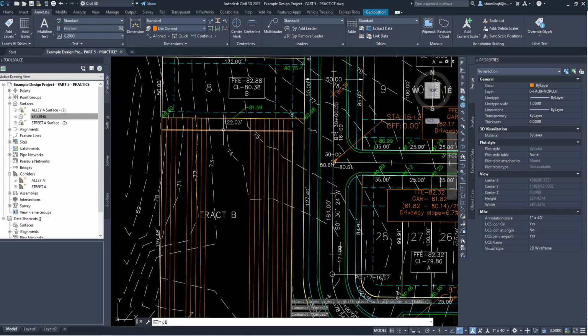So it's basically going to tie into, if I go 69.6 minus 81.59. So this minus this divided by 60.9. 69.6 minus 81.59 divided by 60.9. The slope here is basically 20%. It's 19.68.